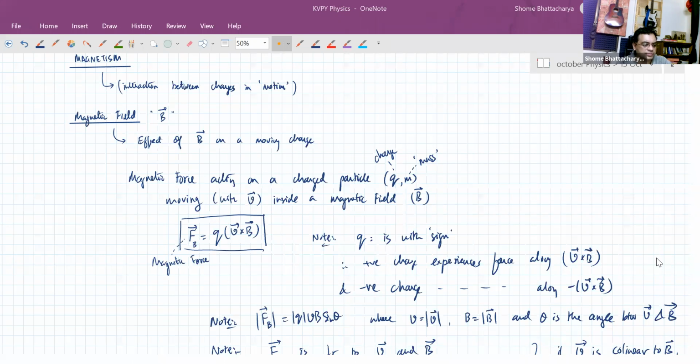Yashwardhan, generally speaking, electromagnets are stronger than natural magnets. So obviously a solenoid will be stronger. But to make the solenoid's magnetic field strong, it's not just the coil of current which is important, but at the axis of the solenoid, we have to place a magnetizable material. So that kind of a material is called a ferromagnetic material. So if we place at the axis of the solenoid a soft iron core or something like that, which is a ferromagnetic kind of material, then that strengthens the magnetic field a lot.